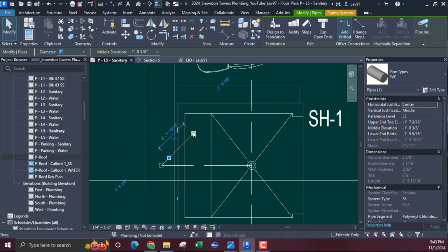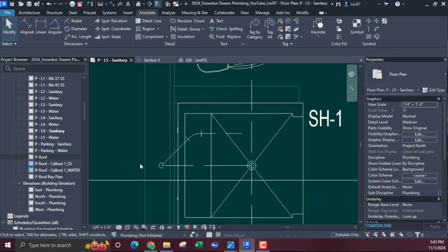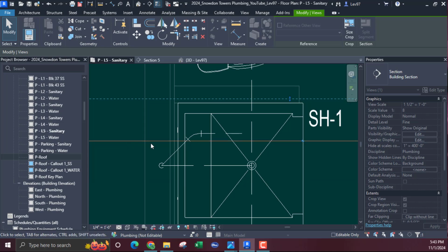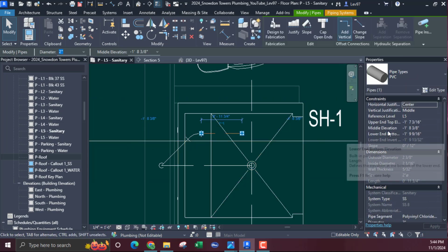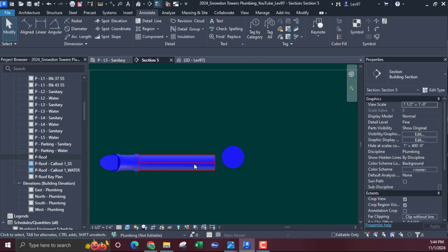So what I'm gonna need to do is come here and make another elbow here. And let's look at that guy and see where we are. I think I'm above. Let's just look at our elevations. So middle elevation is 1.8 and this is 1.7, so I am above. So what I'm gonna do is coordinate this so that it's going to be aligned with this vertical or this horizontal. They're both in a horizontal plane. So I'm gonna go here and it's off just a little bit.